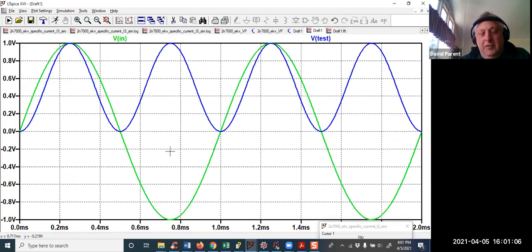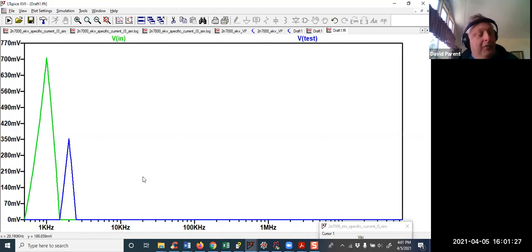It never goes negative, the blue line, so there must be a DC offset there, right? But on the green line, you can see that the time it spends on is equal to the time it's spent off. The Fourier transform strips out the DC information as part of the algorithm. All right.